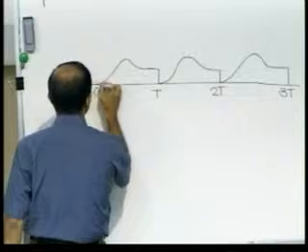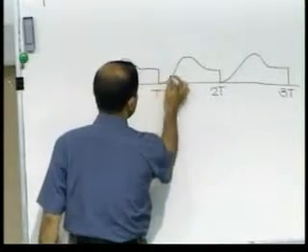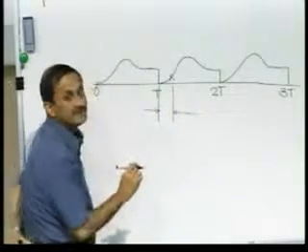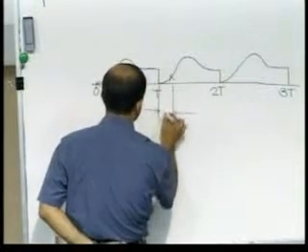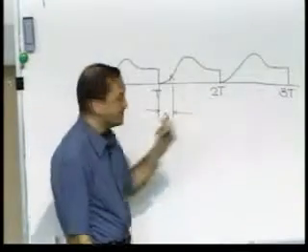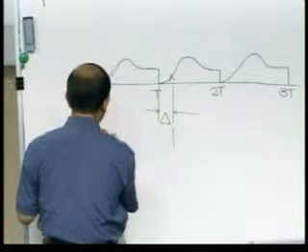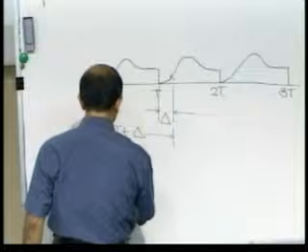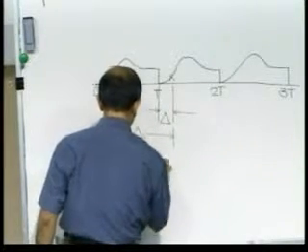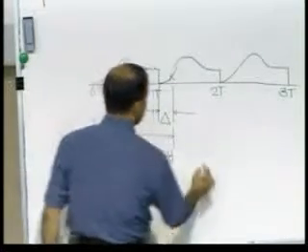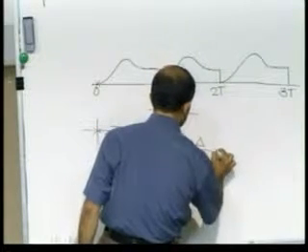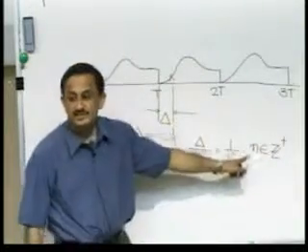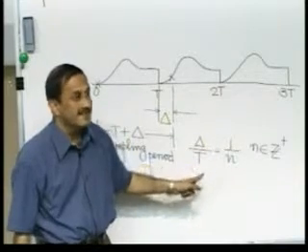Let us take one sample here. The next sample, not here, but here. That means at a distance delta away from the beginning of the period. The next sample shall be taken so that the sampling period here becomes T plus delta. And we assume here for the moment that delta by T is 1 by n, where n is an integer. So, delta is a fraction of the form 1 by n, it is 1/nth.